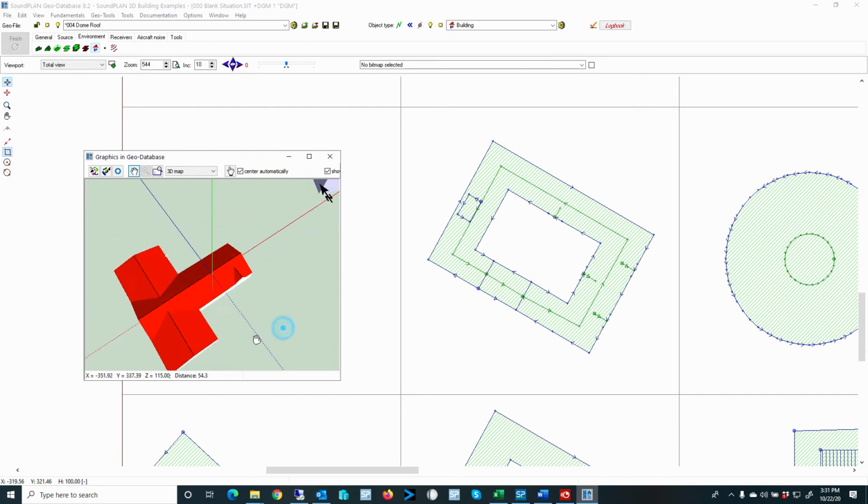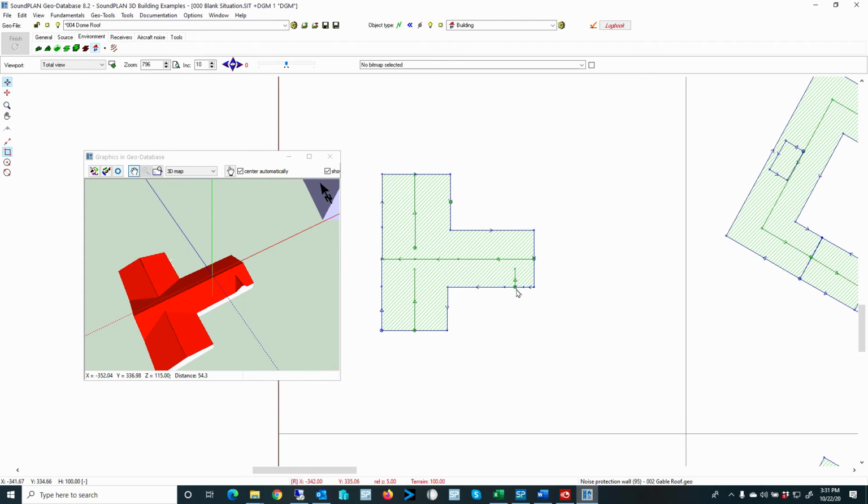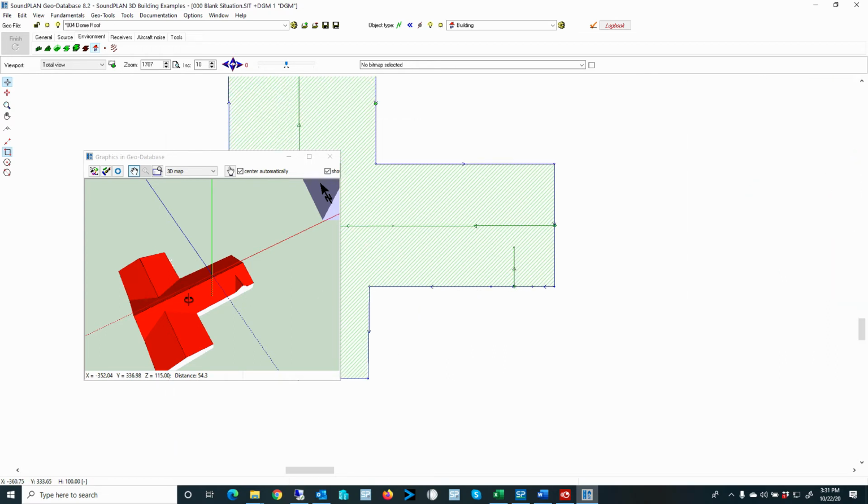So here again we have hitch buildings, a gable right here. So here the gable is just a small piece of a ridge line that overlaps with the wall. Now here, to create this way of how it basically wraps around this gable, I added additional coordinates to the right and left, and then with that the program has corners or coordinates that it can adjust the roof or the outline of the gable.